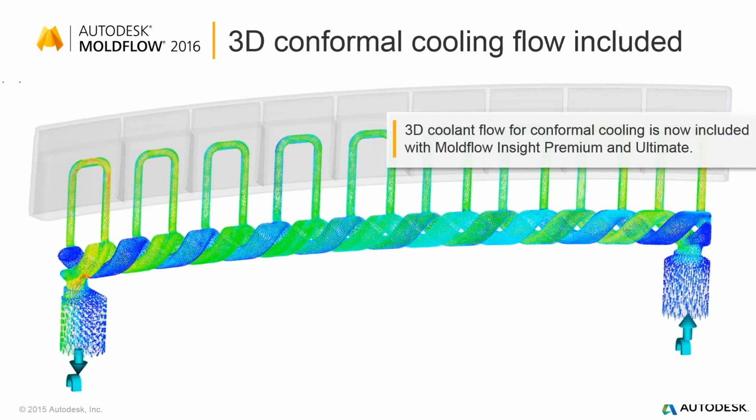Another thing we did in this year's release is add full conformal cooling, now completely within Moldflow. Whereas in the releases until now, the 3D flow inside of the cooling channels could be done, it required an Autodesk CFD license for both the solver as well as the design study environment, so the user interface.